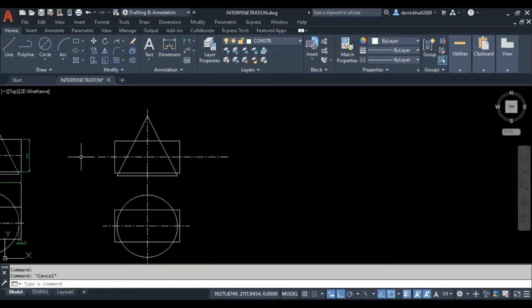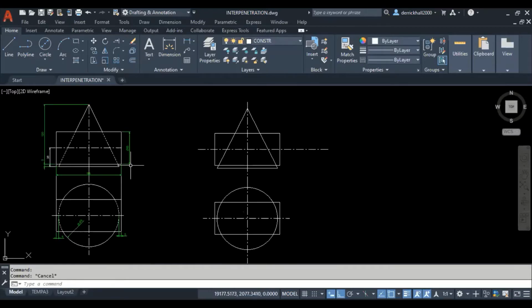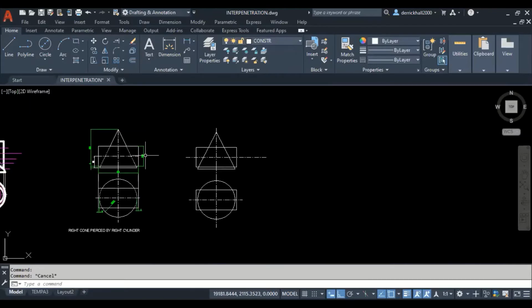Now, what I can do is draw an end section of this and divide it up. If I look from the right side, or whichever side, I'm going to see a circle. So I can draw a circle to represent the cross section of the cylinder and divide it into a number of equal parts. It's diameter 65.